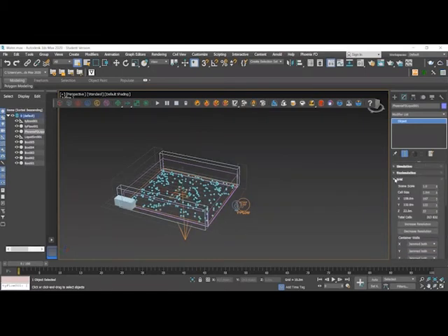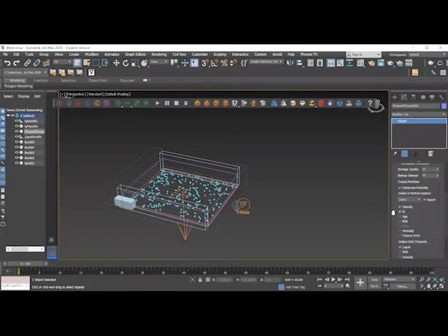So you can unexpand grid and then choose output, and then you want to browse for a folder where you want to save it. Then also scroll down and make sure velocity is ticked. You can unexpand output, and in preview just make sure that show mesh is ticked. And in the same section you just want to disable particle preview.